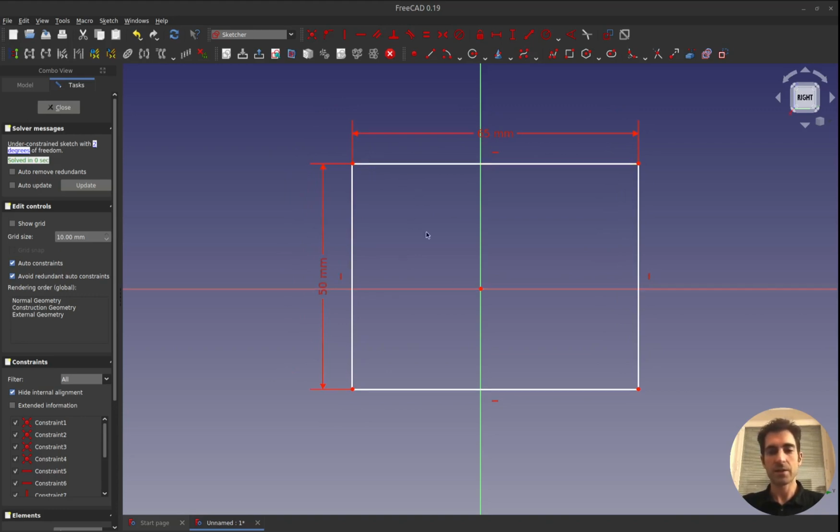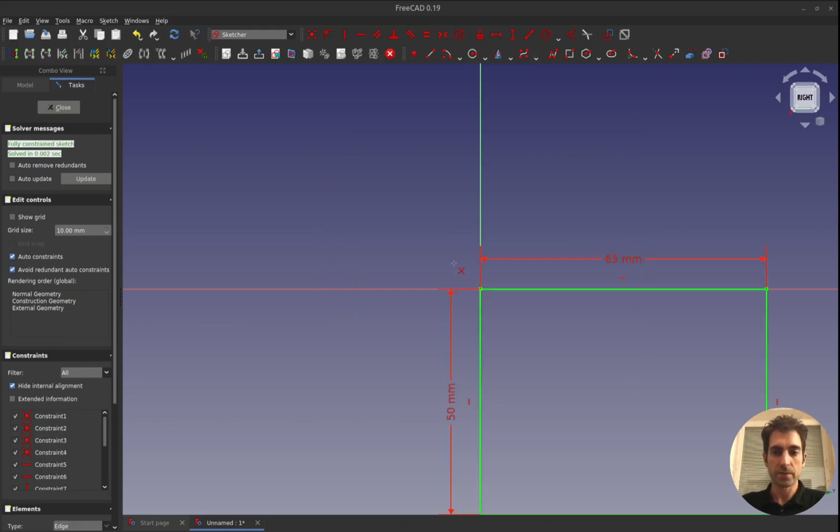So how can I fix the position? For example, I can say the distance from the top to this middle line, which is the axis, is 35 millimeters. Or what I can do is also use a constraint, right? So I'm here using a coincident constraint. That means this point that I'm choosing and this point in the middle, which is just the 0, 0, 0 point, are coincident.